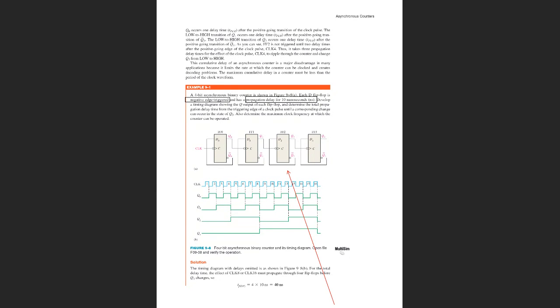The previous example was different. They were triggered by the positive slope of the clock, and the connection of the next flip-flop was with the negative output of the previous flip-flop. So now the connection is slightly different, but it's acting exactly the same way. It is a counter.